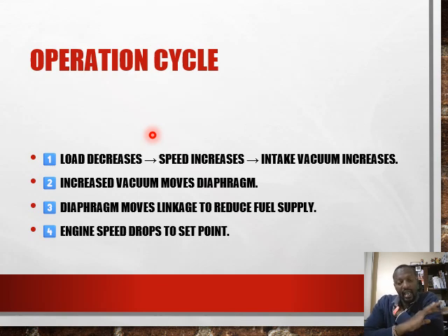So this continues through that speed range until a point when the driver tries to do maximum speed and is depressing the accelerator pedal flat out. This opens the throttle fully, and this means that the depression has now almost collapsed. But again, due to the venturi, the airspeed passing over the venturi now creates a new depression, and this depression now acts on the vacuum unit and therefore retracts the pump rack backwards to reduce the maximum fuel, and therefore reduce the fuel that is being consumed.